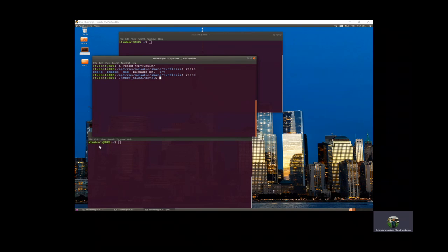Now, I told you that ROS needs to have a master node, and then you also have client nodes. So the first step is to start the master node, right? So let me clear the screen over here, and then let me do cd space tilde, and then okay. Now, first I'm going to start the ROS core. That means this is starting the master.